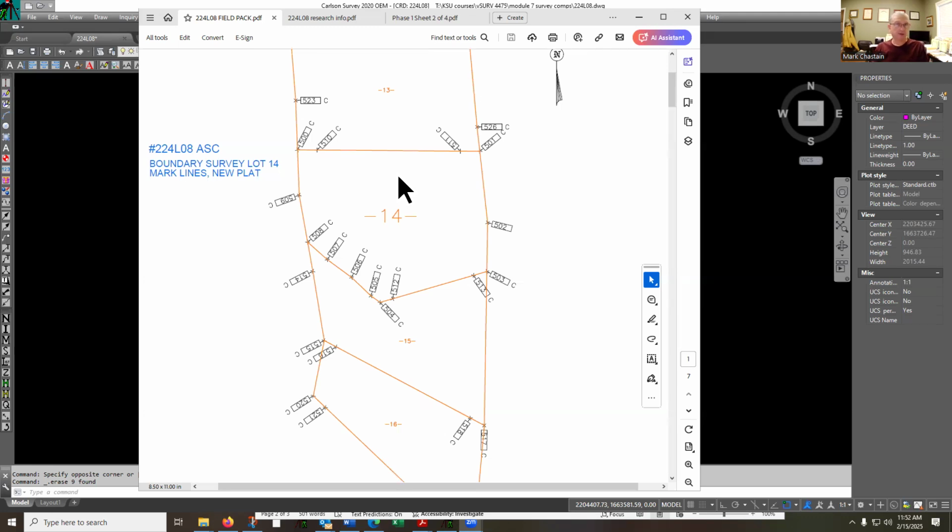So if you stop right there and you say, oh, wow, everything checked beautifully, everything was within a tenth, let's go back to the office, boss, you may have very well just made a big mess because you may have just taken a bunch of erroneous pins thrown in the ground that fit with each other but are not the correct corners. The only way to avoid this and to know that you're not making a big mess like that is to go out at least one lot in each direction to confirm with some other original monuments from the subdivision or accepted monuments, maybe older subdivisions, and know that you are where you're supposed to be.